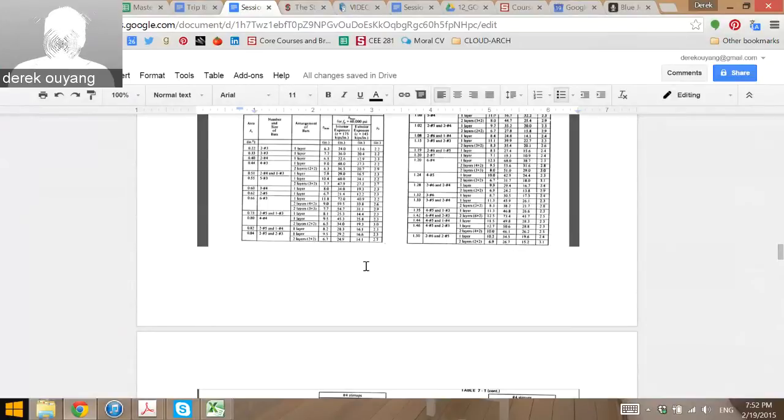In your y direction, you're going to put M, whatever M you're getting out of this, normalized to BD squared, so that you're getting a normalized plot no matter what your geometry is. So that will be your next values on your spreadsheet, BD squared, and then you're using the formula here, right? You sort of set it up so this goes over this side. Then f prime y, just set that up to be 60 KSI. So our graph is only going to deal with 60 KSI.